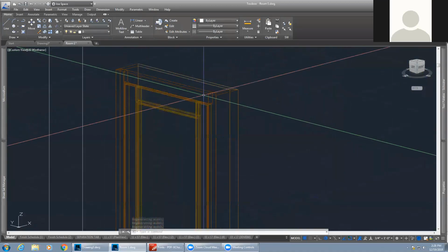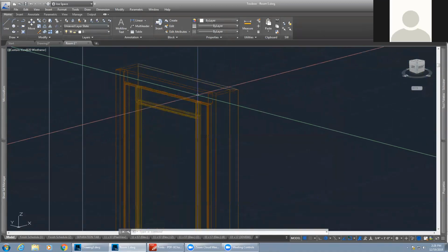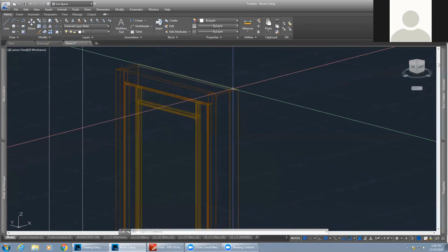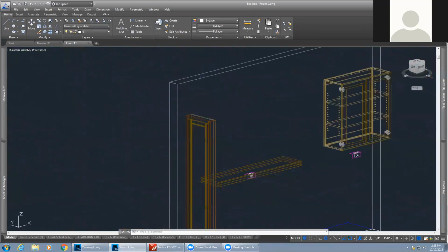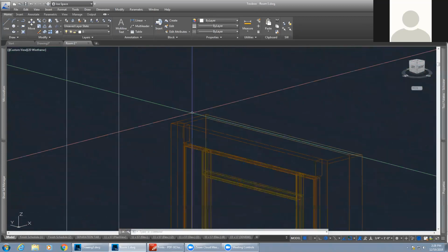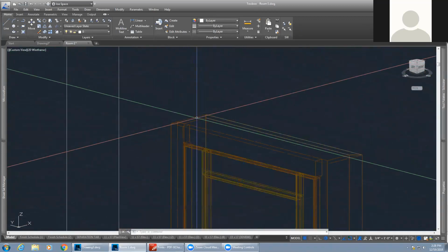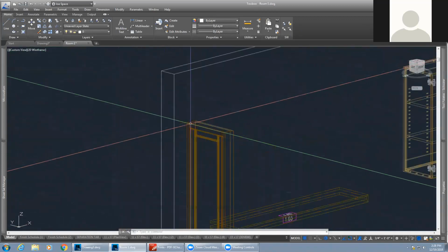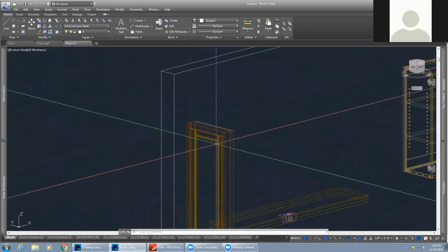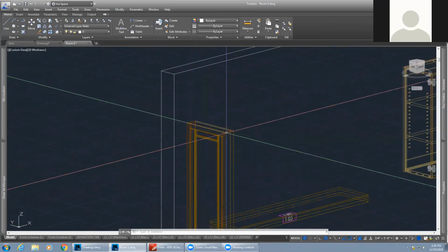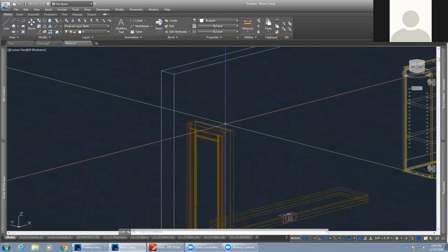So now with a couple of prompts, I added a face frame on the side of that same filler with an inset door inside of the face frame, and closed off the back with another piece of hardwood. So this could be floating out in the middle of a room and be finished all four sides. It can be finished left in face. It can be finished left and right in face. So all of those become prompts.